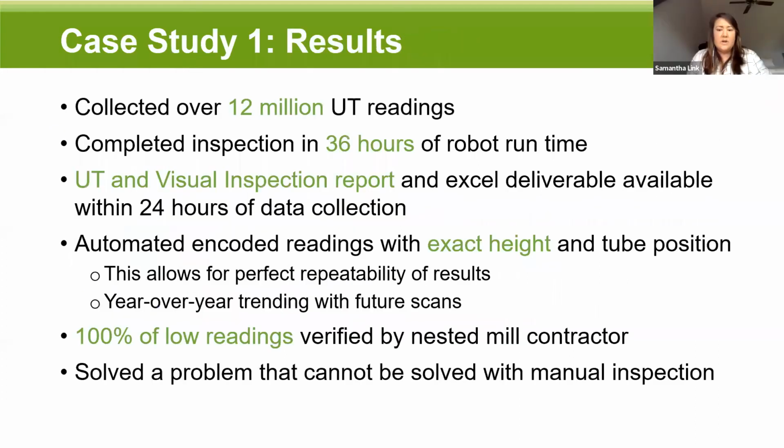Hey, David, does it work on tangent tube furnaces? Yes, it does. Okay. And then can you scan over paint? Do you need a specific standard for this inspection? Yeah, so we can scan over paint, depending on the makeup of it. With a lot of these things, we need to understand exactly what the composition of the material is. And it's the same thing with things like composite and overlaid tubes.